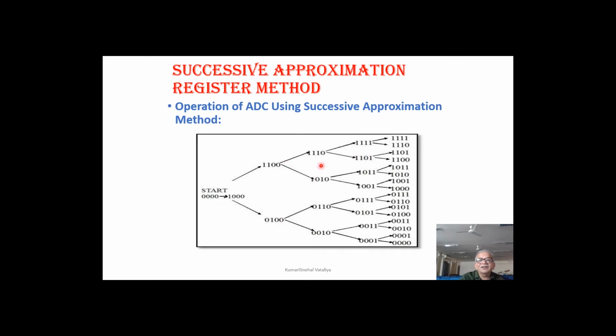Similarly, next you have got 4 positions, either high or low. So if you compared with 12, you either compare with 14 or you compare with 10. Earlier, if you compared with 8, you either compare with 4 or you compare with 2. So that way the process will go on, depending upon what you have compared earlier, your next number will be decided, either high or low. And finally you will have 8 different values for the fourth bit, but only one of them is used, so one per bit.